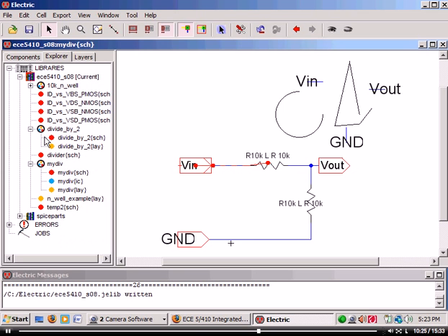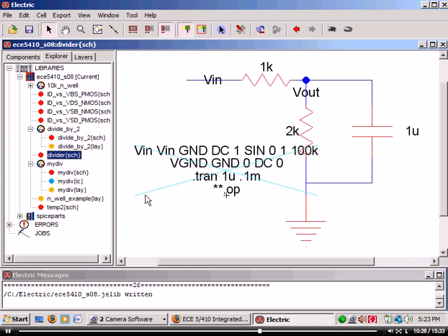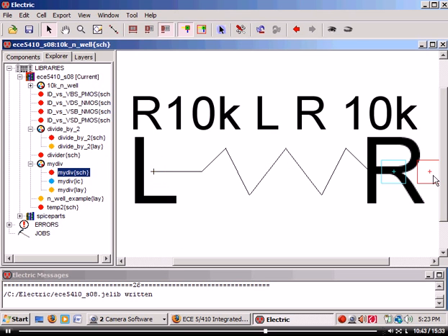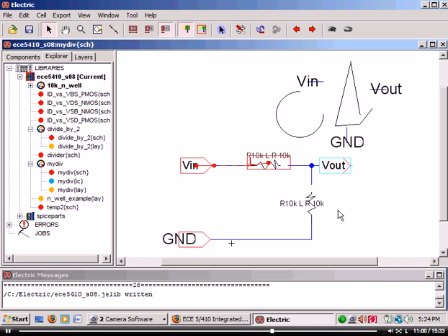If I go look at this divider here, let's see. Where's a good divider? Here's a good divider. If I go edit this cell, many people did this, and when I see a circuit, I want to see continuity. I want to see a circuit going down. So I do a Control Down, and let's say that I move, let's leave that there so our circuit stays connected. Let's say I go here, press Y, and I move this over, move this over, move that over, press Y, Control Up, and now I look at the schematic, and I don't see a connection around the circuit. And so that bothers me.